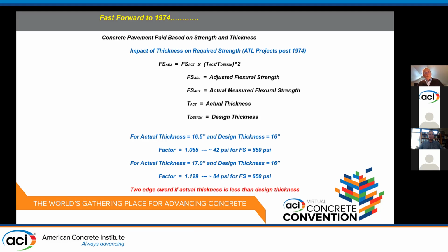But it's a two-edged sword. If the strength is low and then the thickness happens to come in low, you have a problem. And one time I was on a project, it was an Air Force project. Contractor had put in concrete, he had low strength in his beams. We went in, did all kinds of testing, tested compressive strength, tested split tensile, and concluded that yes, the strength was low, but he had put in 12 3/4 inches instead of 12 inches.